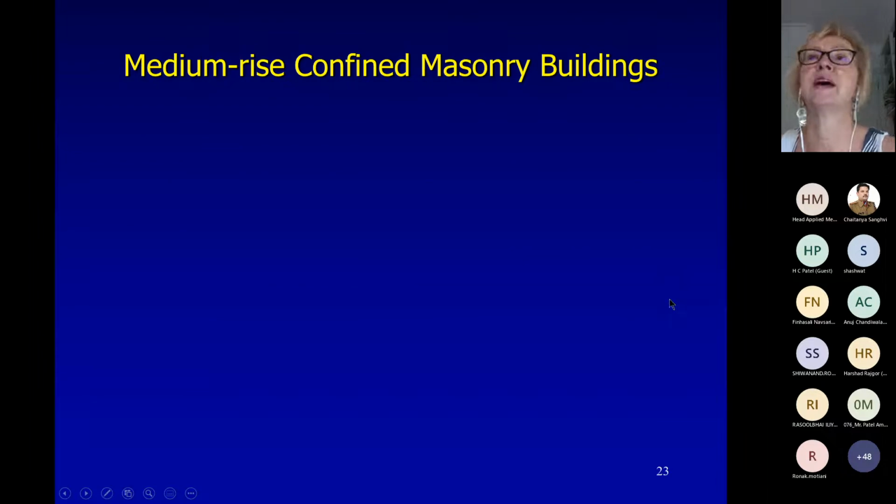So this is more or less all I could say about these single family buildings. As I said at the beginning, small, very minor damage, no collapse. The buildings were repaired after the earthquake, and they were not retrofitted, just repaired. The cracks were sealed, and they were replastered, and that is all.